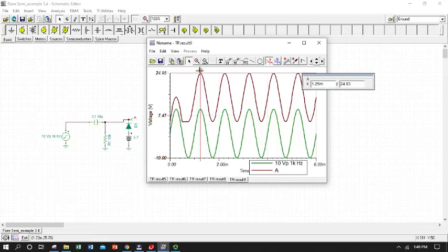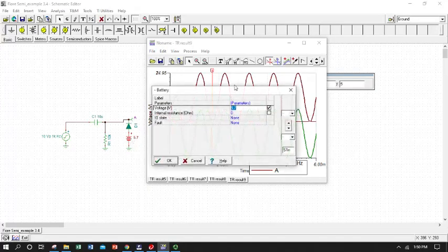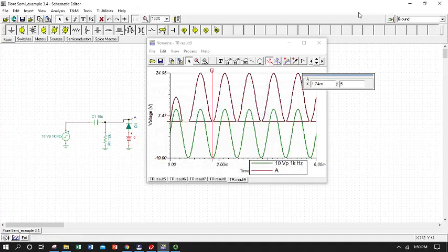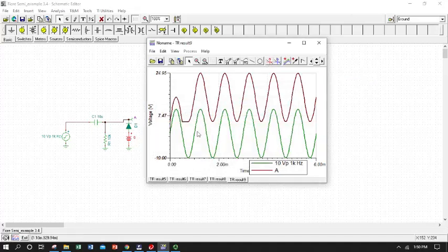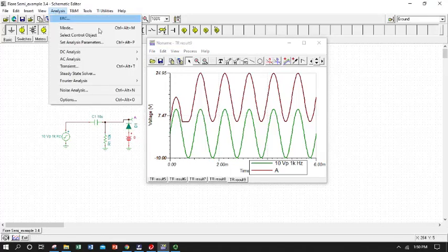So what we would say is that we have clamped our input waveform to 5 volts effectively, which is approximately this minus the forward bias voltage. If we took this source out or reduced its value, maybe we'll call that 0, and reran our analysis, we would expect to see this peak being clamped to just the forward bias voltage of the diode.